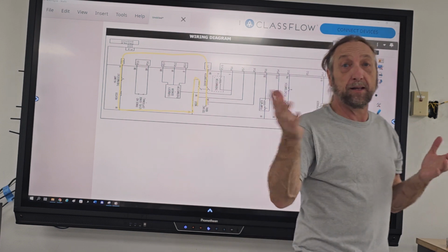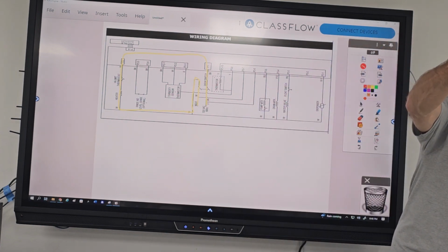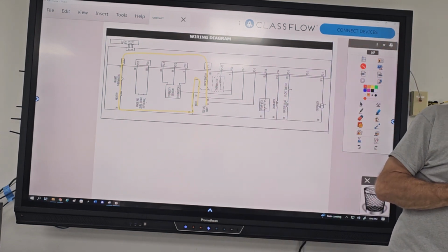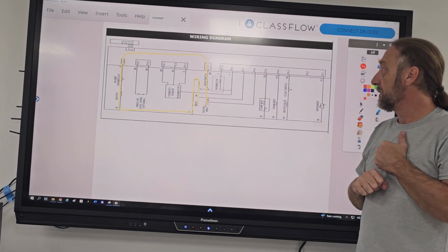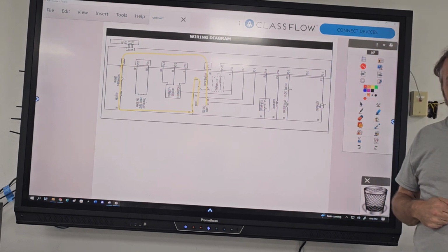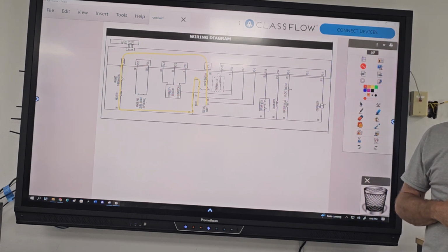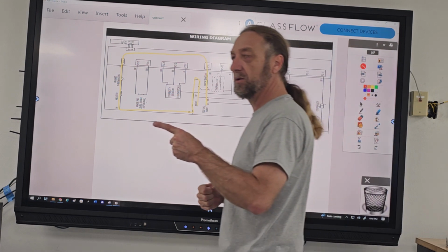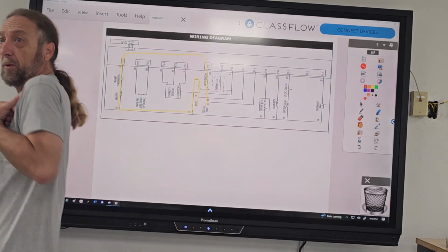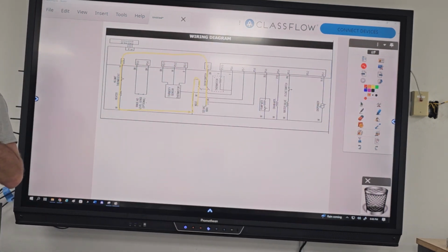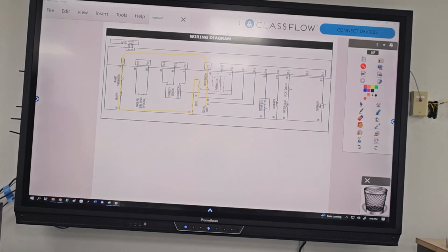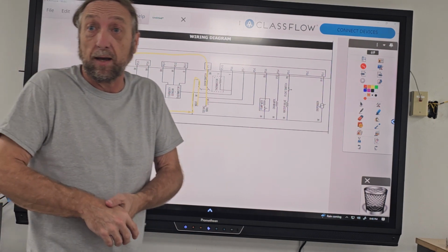So, someone got an idea? Gene, you got one? Which one? The door switch, the heater, the element thermostat. No, hold on, give me one thing. The door switch. No. Why not the door switch? He said door switch, I say no. Am I right? Am I wrong? Because we already checked the door switch is working. I said everything else is working. Everything works. Just at the end of the cycle, the dishes aren't dry.